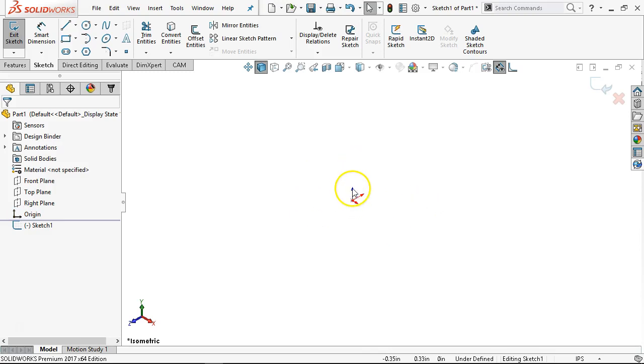I'm going to see the vertical component of the part. The horizontal component of the part is in line with the horizontal component of the sketch, and really I'm only concerned with, at this stage, that red arrow. So I go back to control 5 because I'm in the top plane, or control 1 if you're sketching in the front plane, picking up each of those items.